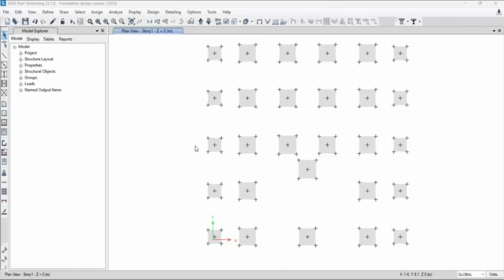So meaning your footing is actually sinking, due to the load coming from the superstructure. And we don't want such a scenario, because if this happens, it is going to lead to structural cracks in your wall above, right? So we don't want this to happen. So that is why we need to check for this. We need to check for the allowable settlement.